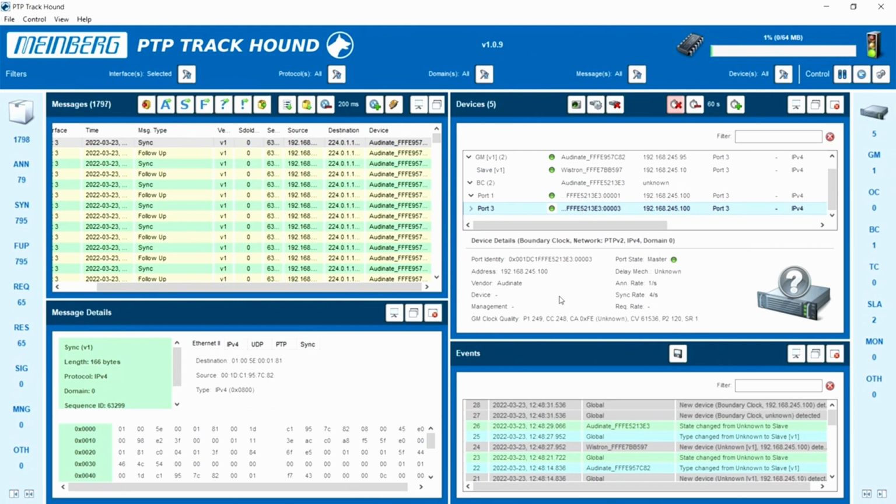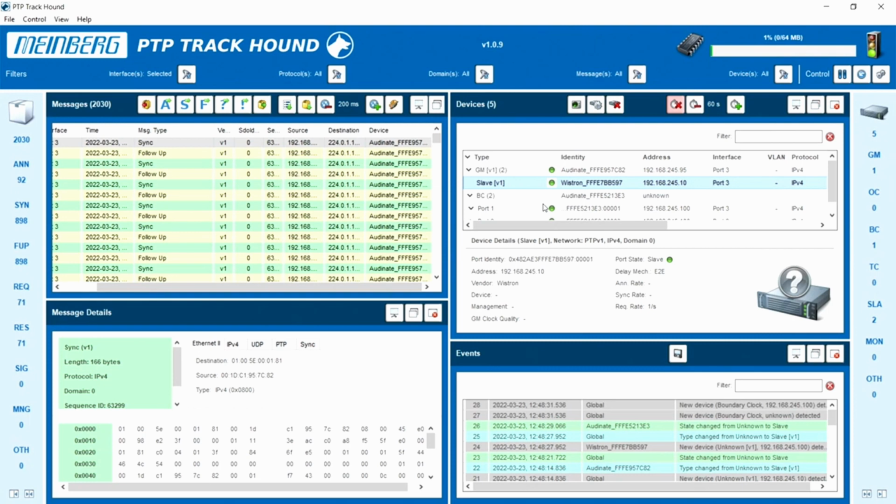So if I dig deeper into the whole thing, you'll see here PTP V2, and if I hop over to here, PTP V1. So this allows me to see how many masters. Why is that interesting? Next time you're on an AV system that has AES67 and Dante, open up this tool and look how many clocking systems you have. Because we're working on a very small scenario right now, which is my Dante and in a small switch context.